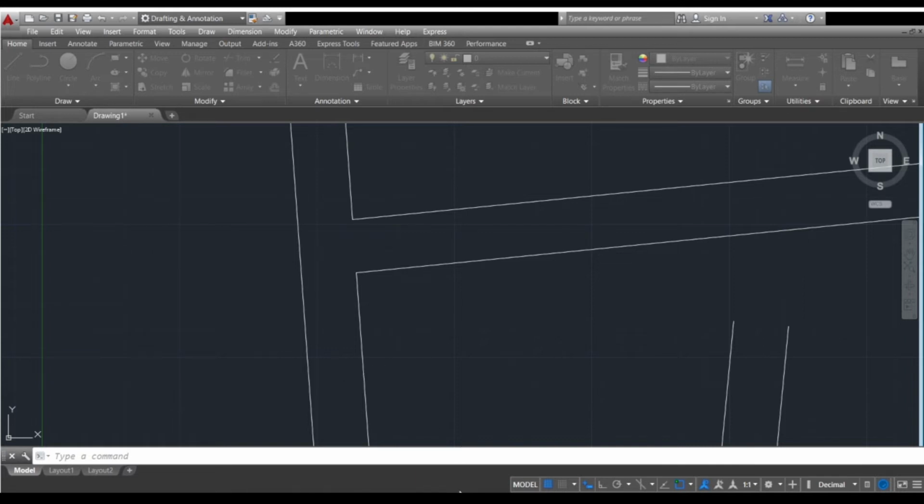So you can see from this other window a preview of the new style that you're making. And you can also change the line type of your multiline. So you can make it a dash, dot, or whatever you want. So, okay. We already have our ML style. So I will just set it to current.